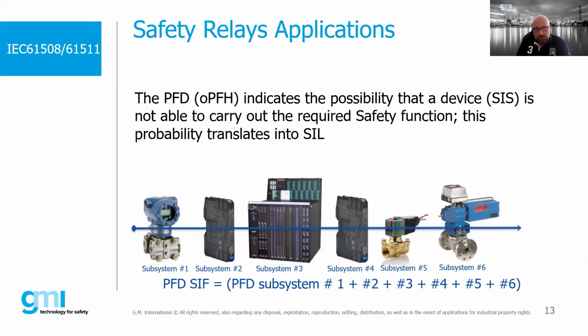Power interfaces, such as safety relays, act on valves, sounders, beacons, and other actuators, and allow us, in case it is required, to drive the system into a safe state. The important thing to note here is that every single element of the SIS must be sized according to the required SIL level to achieve the tolerable risk level. All the components within what is called the safety instrumented function, or SIF, including power supplies, are safety related, so they must be SIL rated. And this is what makes a loop safe. Let's go to the next.